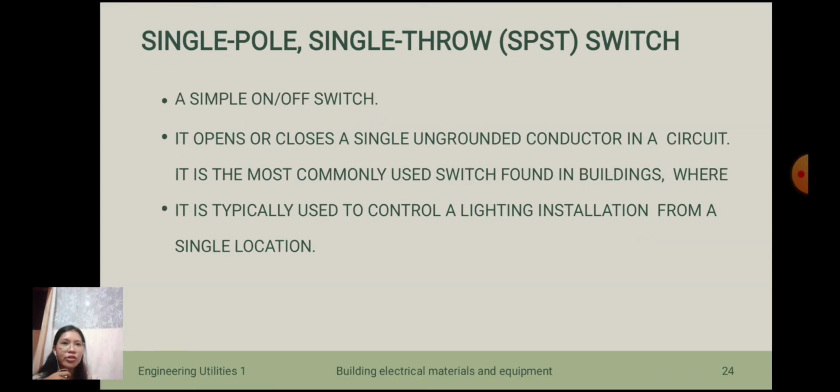So we have here the single pole, single throw, SPST switch. So a simple on or off switch. It opens or closes a single ungrounded conductor in a circuit. It is the most commonly used switch found in buildings, where it is typically used to control a lighting installation from a single location. So ito po yung kadalasan natin nakikita, a single pole, single throw switch. Kung saan, for example, we have one light, a pole, and then a switch. So, single pole, single throw. If i-open mo yung switch, may function na isang pole.